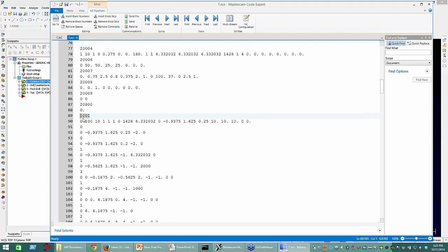So the NCI G code 1 calls the start of file post block inside the post, and then passes this line of parameter data to MP. MP reads each one of these parameter values, starting from the left and moving right, and loads each separate parameter into a variable to hold that piece of data. At that point, MP starts processing from the end called and processes all the instructions in that post block. Once that particular post block is done processing,